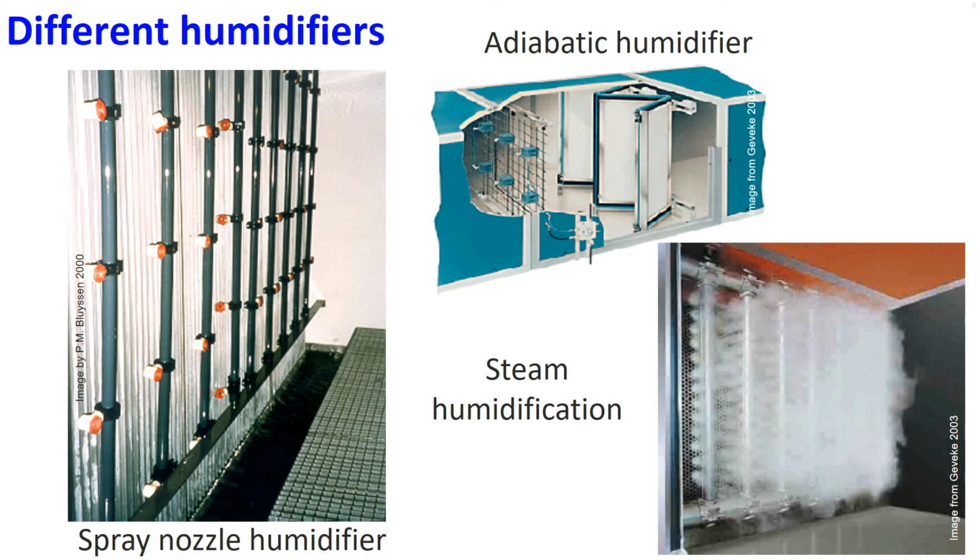Then humidifiers. Humidifiers increase the amount of water in the air. Humidification can be accomplished with water, such as the spray nozzle humidifier and the adiabatic humidifier shown here, or with steam. Badly installed and or badly maintained humidifiers can pollute the air. In particular, microorganisms play an important role in this polluting effect. But disinfecting and demineralization devices or agents can also contribute to polluting the passing air.